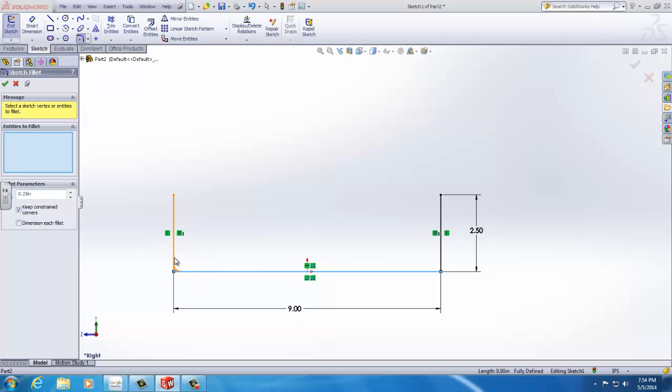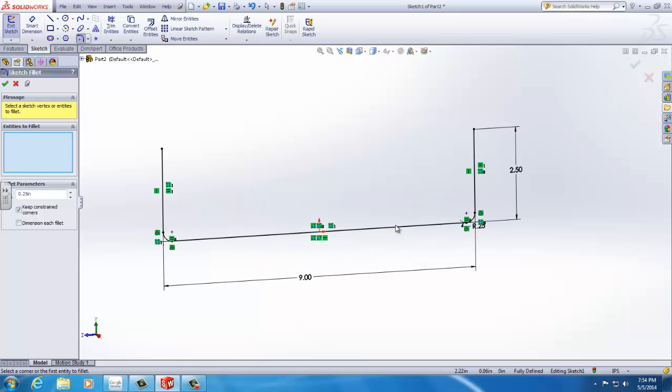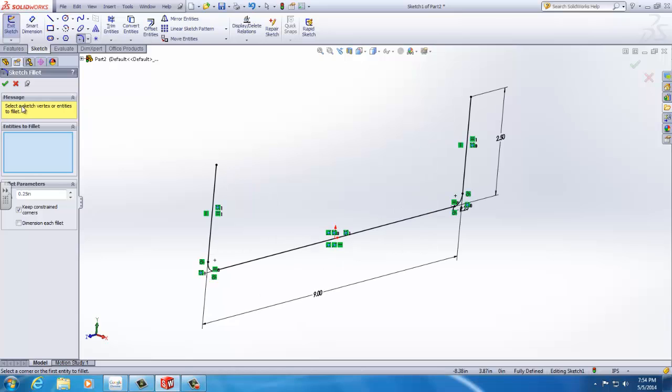The radius changes based on the machine you use. Playing around, you'll see. And so we click the sketch picture. It brings up the window where you want to open up that sketch picture with 90-degree angles. It should be in your L drive. So we have something like that. It's all in black, which is good. It has all the relationships and everything. And we open it up.